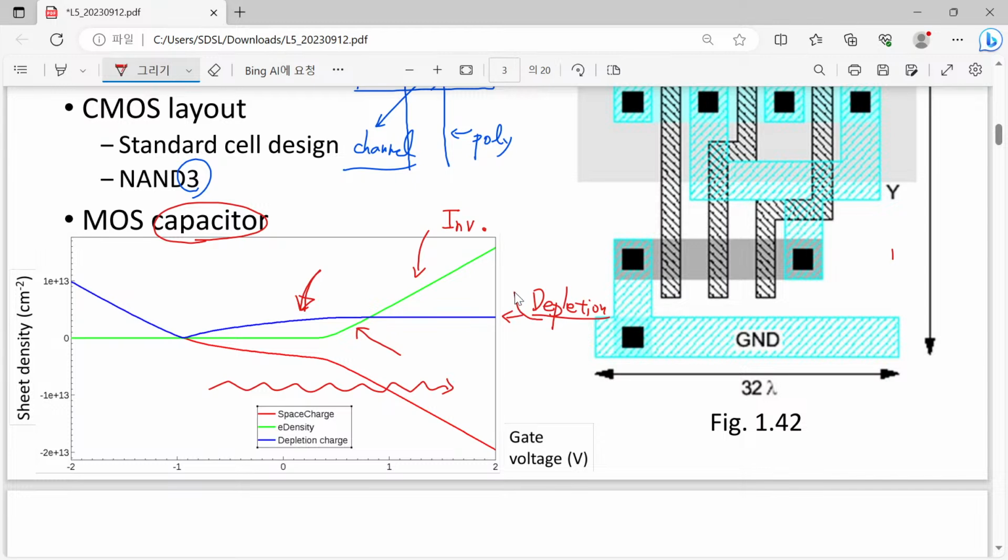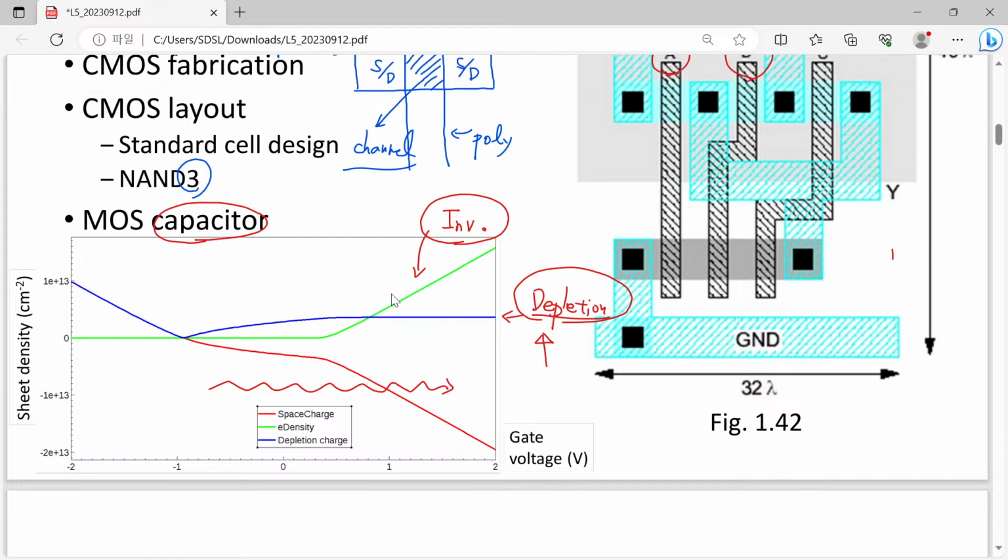In the case of depletion, this is not related to an increase of conductivity, so there is no free carrier involved. However, in the case of the inversion mechanism, it is directly related to the increase of our mobile carriers. So simply speaking, we can postpone the occurrence of this inversion behavior by the amount of the threshold voltage.